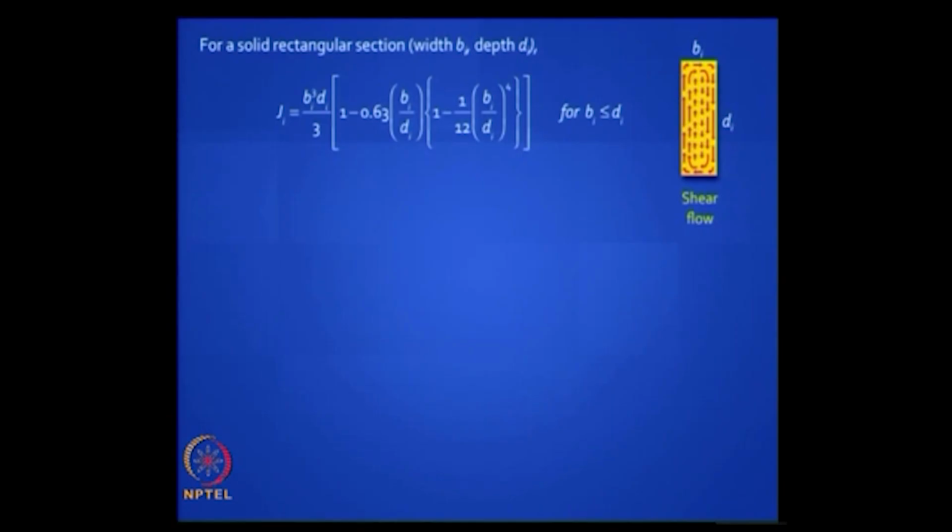And the shear flow is as shown in that picture. If it is subject to a clockwise torque, the shear stress is 0 at the four corners, though the distances are maximum from the center. That is because of complementary shear requirements.